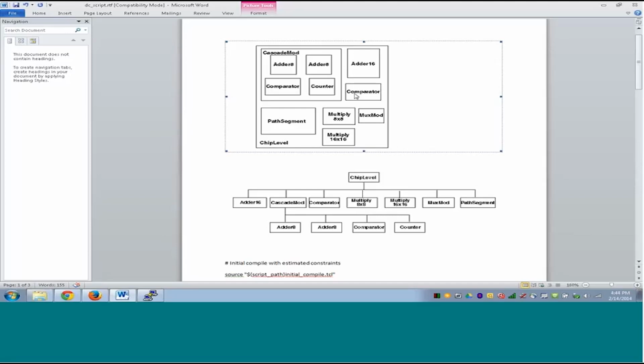When you want to do chip level synthesis for a big chip, you cannot just feed in all the RTL files and do synthesis. It is not feasible, first of all because of the capacity limitation of the tool. Secondly, even if Design Compiler was capable of parsing so many files, synthesizing at chip level is not intelligent.